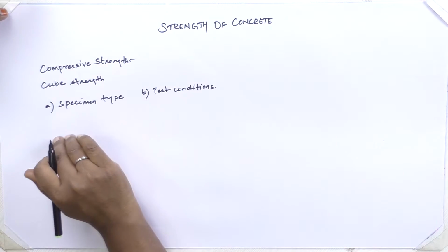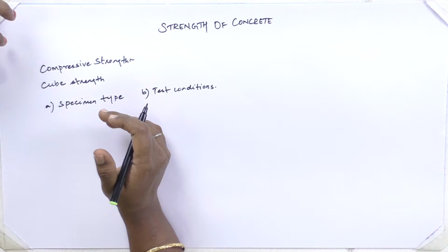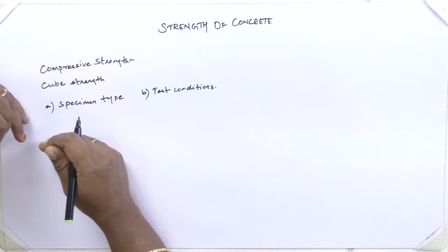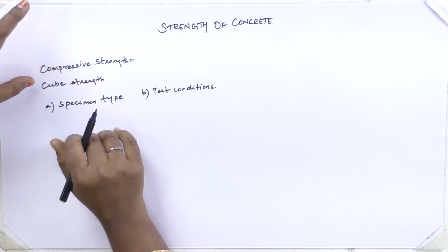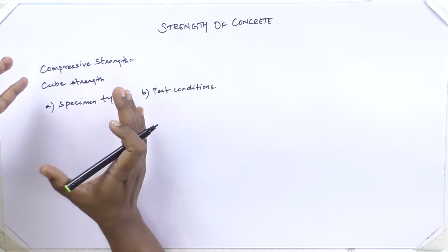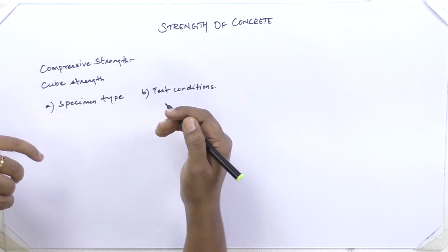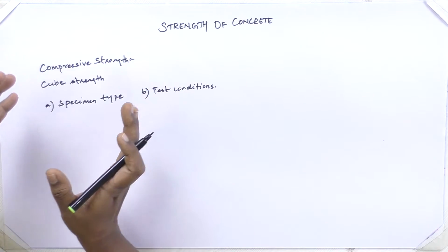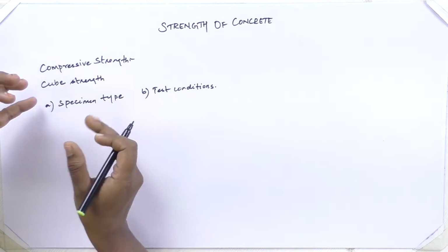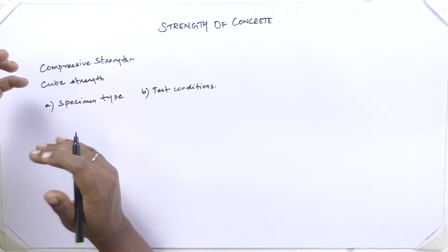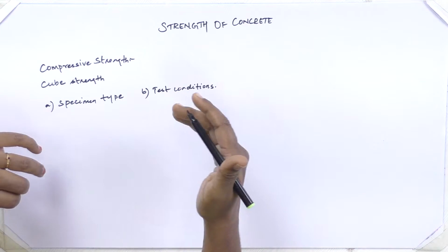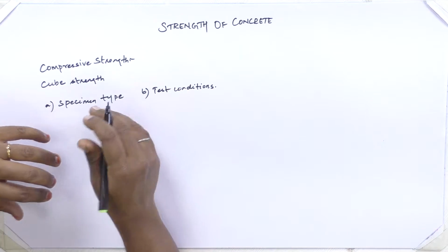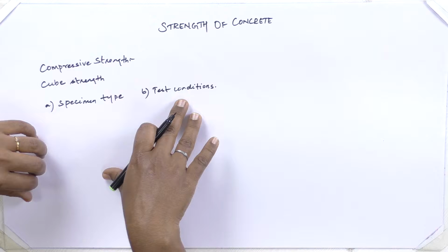For estimating the cube strength, I am preparing separate cubes, and I am not taking them from the structure. And for structures, again I am casting separately.